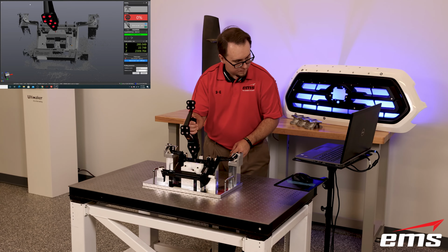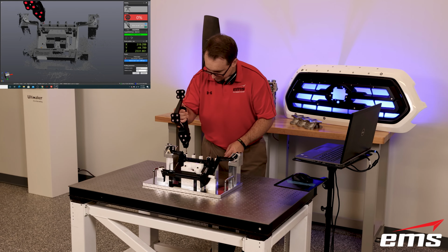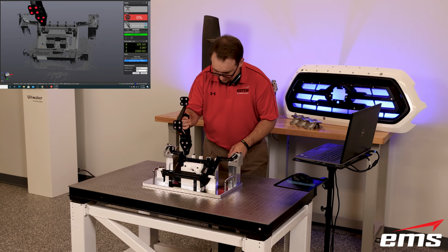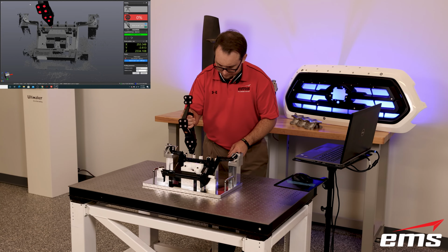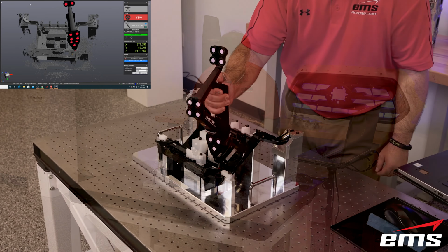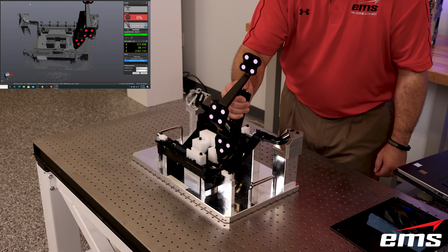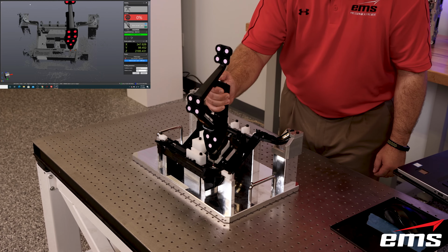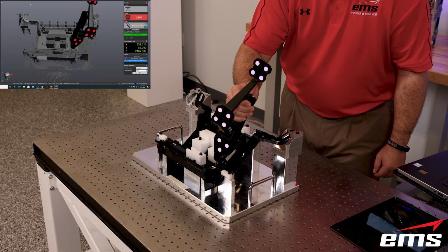Sometimes for small holes or parts that have thin edges, probing is a really good way to go because you can actually make contact with that probe, either down in the hole, or you use a probe tip that's big enough to sit in the hole a little bit to find the center of the hole. And then again, for edges and other thin features, or down inside thin cavities, probing is a good way to go because you can make that contact. But again, it can be used typically in conjunction with 3D scanning.